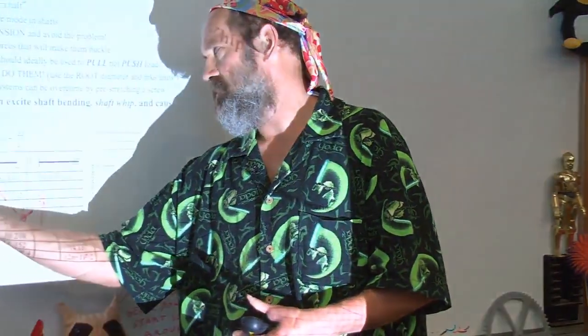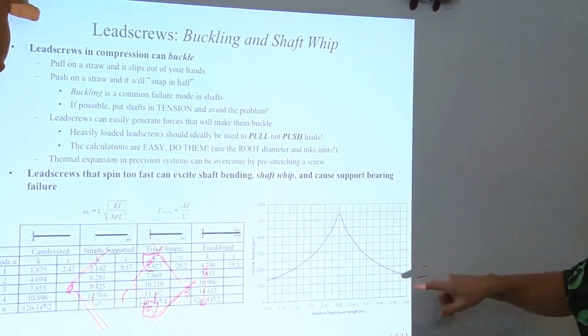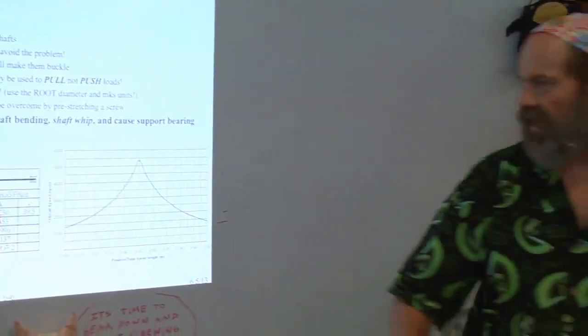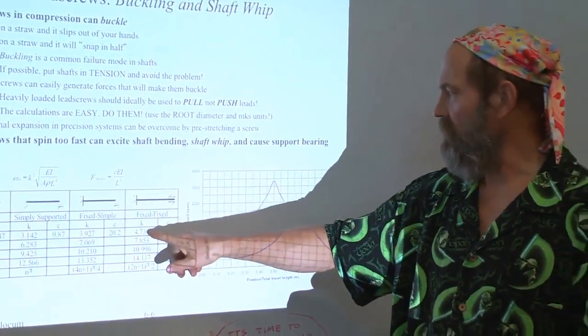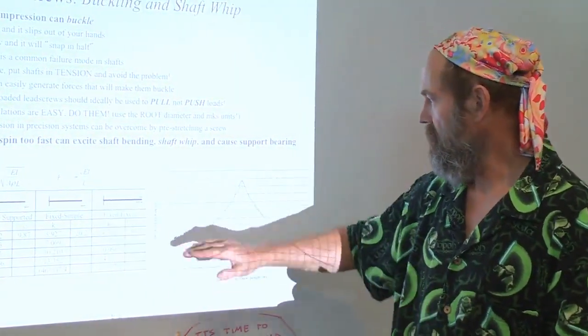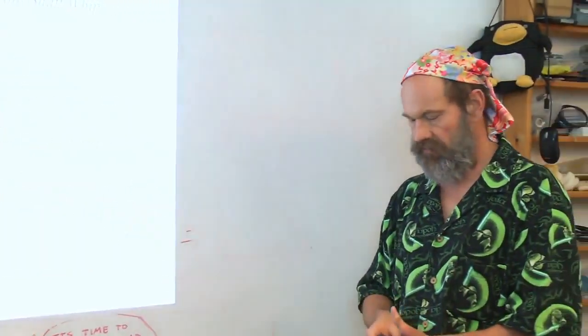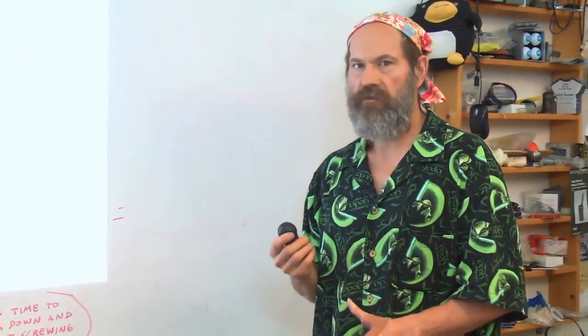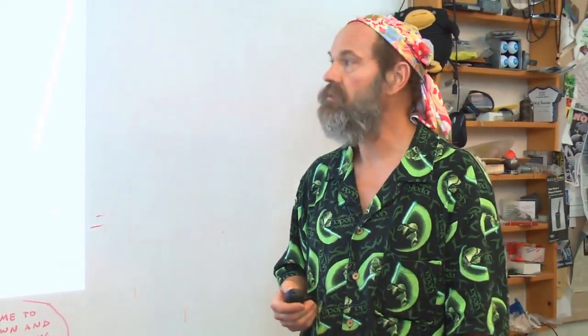Do you, based on is it a high-speed machine, are you happy with simply supported beam and the natural frequency you get, and hence the type of velocity profile you can achieve? Or do you really need that fixed support so you can have your first natural frequency roughly 50% higher, so you can move your machine that much faster, but it requires a more complicated bearing arrangement. Everything is a trade-off. Fortunately, you now are familiar and happy with writing spreadsheets to do these calculations, including cost estimates.